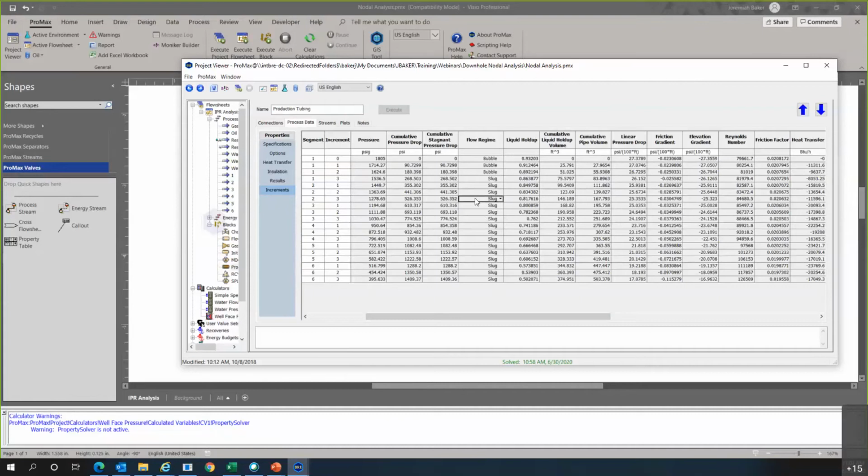It means that your well might be loaded, which means that the gas is coming up, but it's not adequately driving up the oil. And so your production rates of your well are going to normally take a steep drop, a steep dive, if you are in a slug flow case, and that's when we call your well being loaded. And that's a lot of the reason why we have things like artificial lift. So when we talk about artificial lift, it'll be looking at this flow regime and figuring out how to change that.